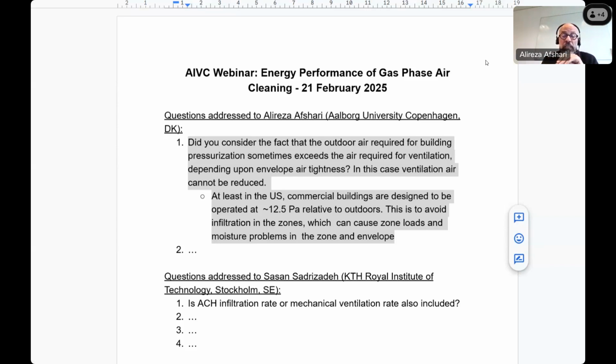And the second is that if you have a demand control ventilation system, you can actually adjust the ventilation rate dynamically to ensure that pressurization needs are met. And in addition to this one, I will say that when you have recirculated air and air cleaning, the amount of outdoor air decreases. So it can also help you reduce the energy consumption while maintaining indoor quality.